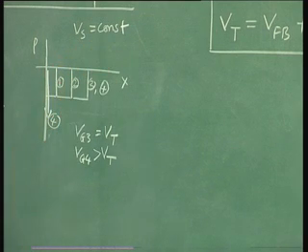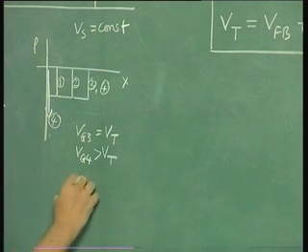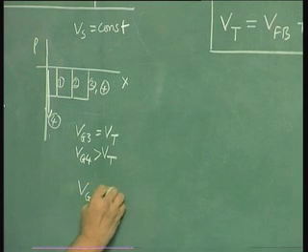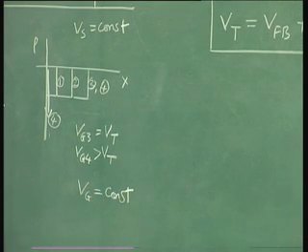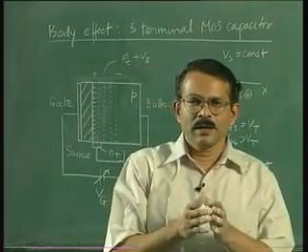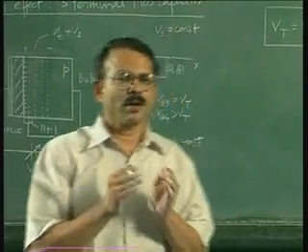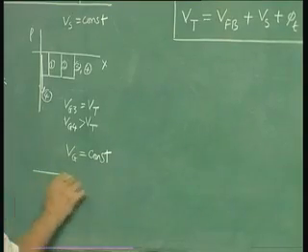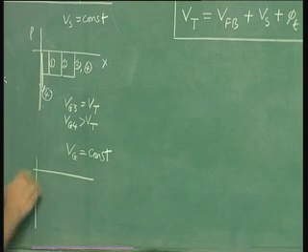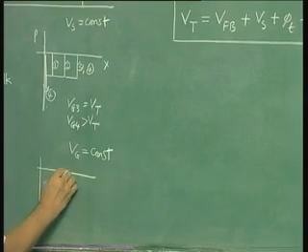If you apply even higher voltage, this inversion charge will go on increasing. Exactly similar diagram, if you would like to draw for the condition Vg is constant and Vs varying, this is what we had discussed earlier. So to complete the explanation we will draw that diagram also. That diagram would look something like this. First you are starting with the condition Vs equal to 0.